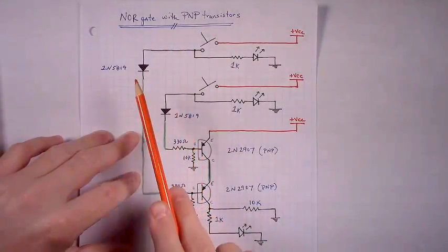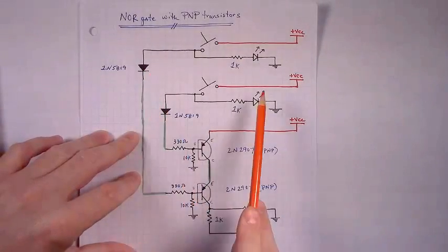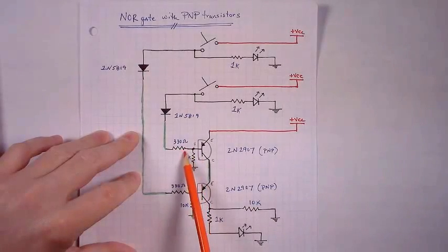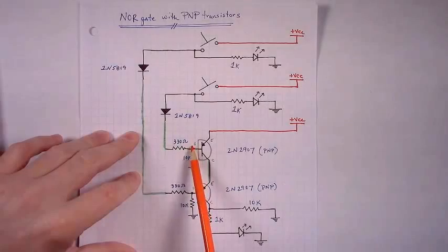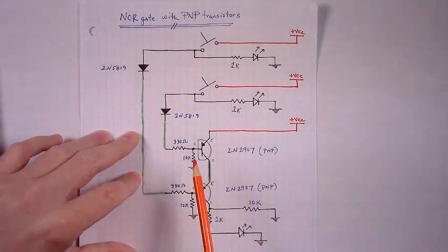You need Schottkys because if you use normal diodes and you drop 0.6, 0.7 volts off of your VCC supply, there won't be enough voltage left to raise the base of this PNP up so that it's no longer 0.6, 0.7 volts lower than whatever's sitting at VCC.